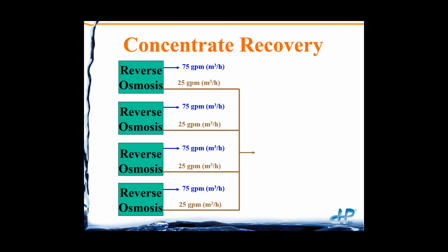So it's actually fairly common today, since most of your drinking water RO units, so RO units that have drinking water as a feed water. Again, many industrial clients purchase municipal drinking water as the raw water. So these reverse osmosis units are operating on pre-treated drinking water. Well, most drinking water can be concentrated more than 4 times, which is what you get with 75% recovery.